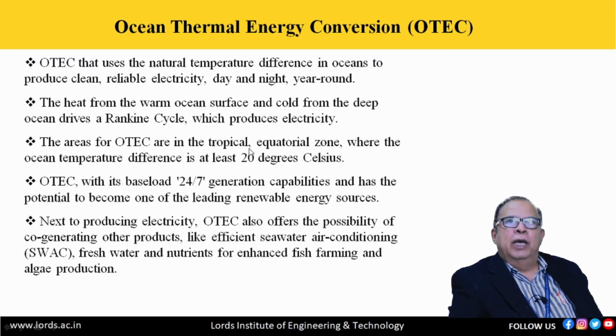Then the areas where these OTEC conversion technologies are applicable are tropical as well as equatorial zones, where the ocean temperature difference is at least 20 degrees Celsius. So we can use this technology where the temperature difference between the surface water and the cold water beneath the ocean, some 400 to 500 meters down, is 20 degrees.